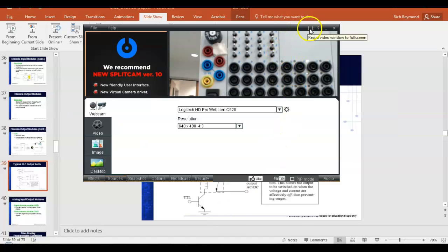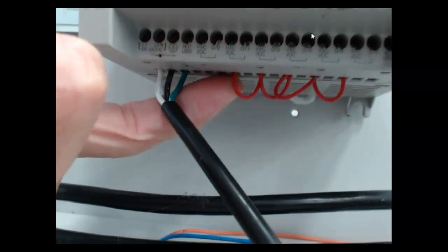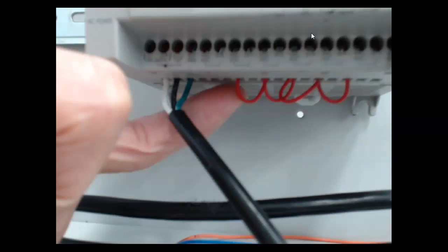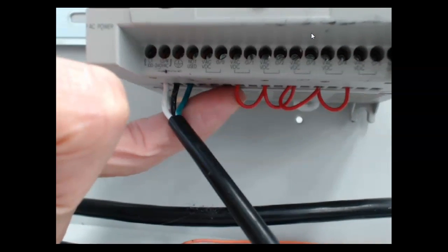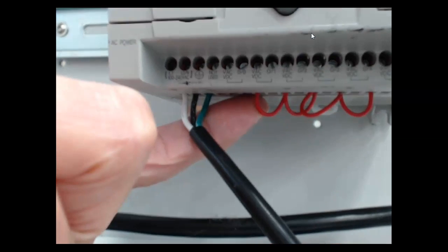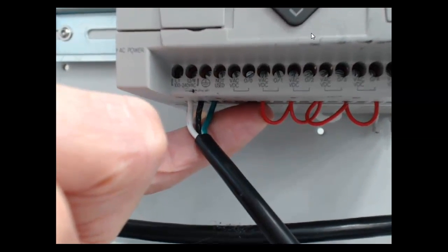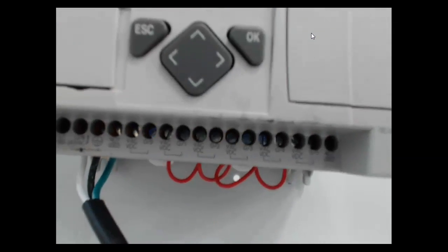And the first thing I do is see all the commons are just looped together. And then what I'm doing is I'm bringing plus DC into the first one. So we'll be using source and output, combine this to be source. But we don't have to do that on these PLCs, right? So what does that relay output have? You decide. What's the disadvantage of a relay output? Seems like that would be the route to go, guys.